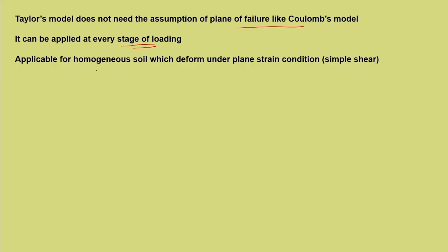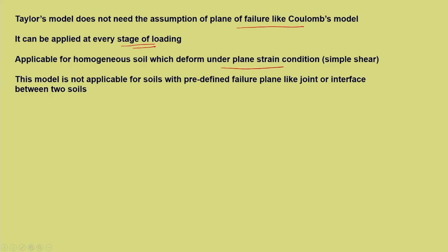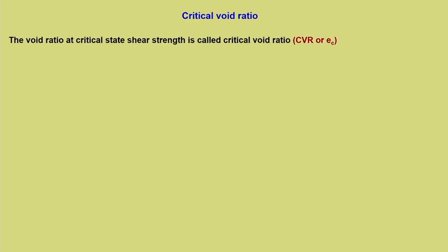So, it is applicable for homogeneous soil which deform under plane strain condition or a simple shear. The model is not applicable for soils with predefined failure plane like joints or interface between two soils. So, here there is no consideration of plane of failure.